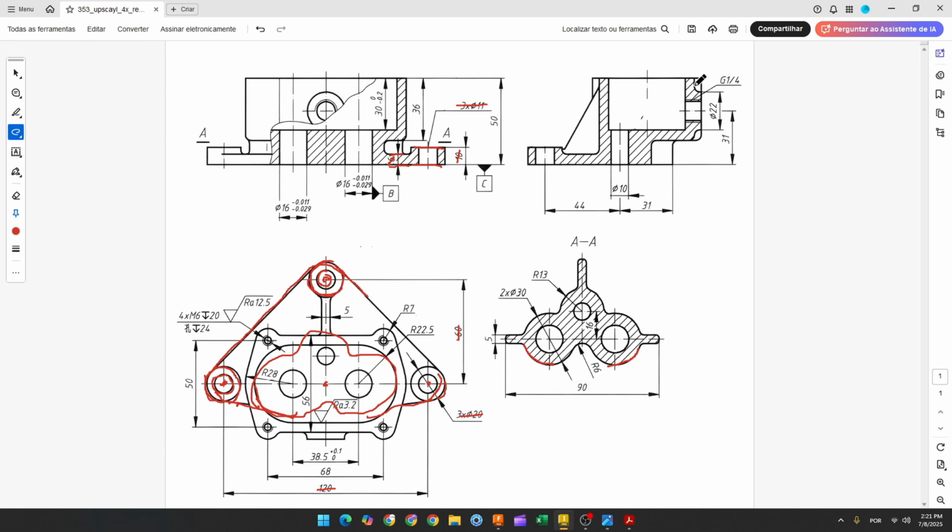Now we need to create this extrusion here with 22 millimeters of diameter, and the distance between the center of the circle and the bottom face is 31 millimeters. The circle here, okay? And we know that the face of the circle is tangent with this point here. Okay, this point here is the same here, so we'll create a line here and rotate a plane here, okay?